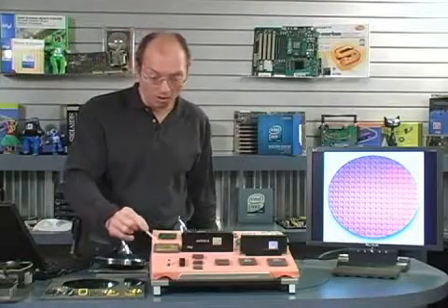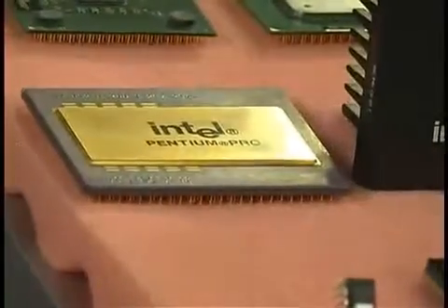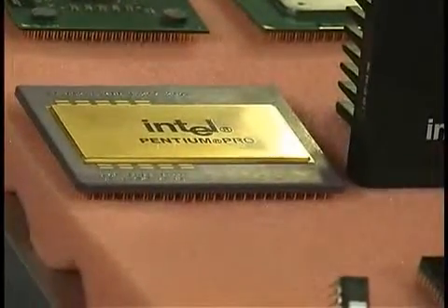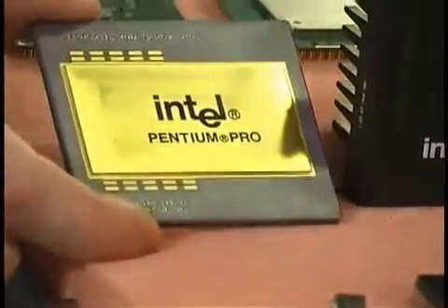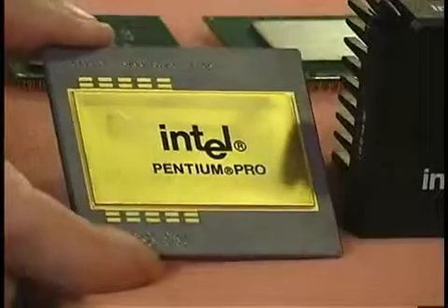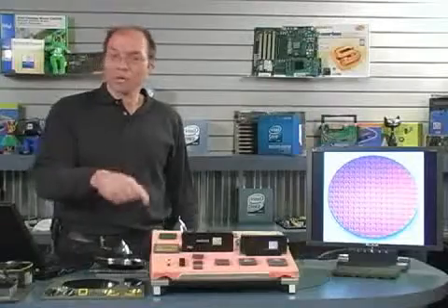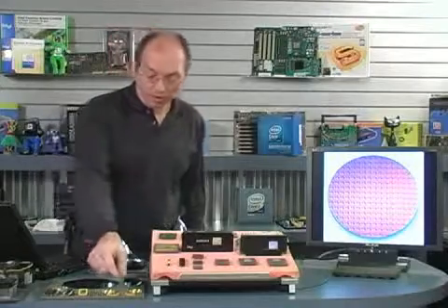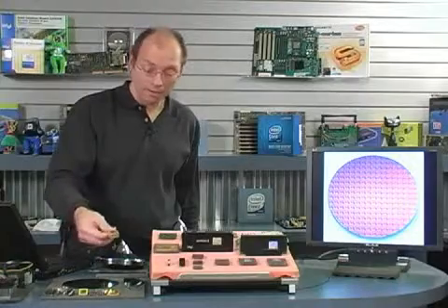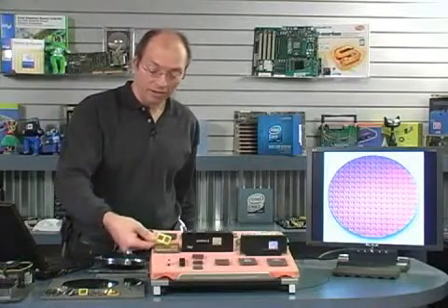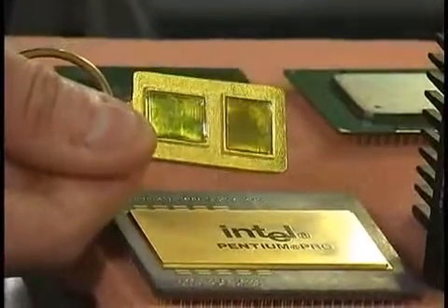This was called the Pentium Pro, which is right here, which came out in 1995. Now, the Pentium Pro was really a revolutionary chip. For one thing, it's huge. It's physically probably the largest single chip I've ever seen. And the reason is because there's actually not one chip in there. There's 2. This, in fact, represents the actual die of the Pentium Pro processor, and if I set it on here, you'll see why this chip was rectangular, because there were basically 2 chips side by side.